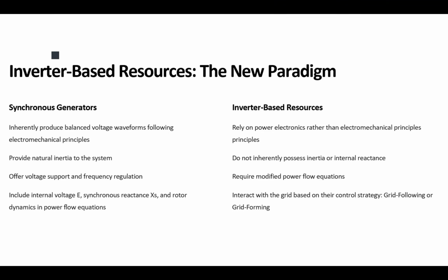We actually started talking about how we could analyze the effect of inverters from a system perspective, and we started with the power flow analysis, which is one of the steady state analyses for the power system, to find out what the distribution of the energy and power looks like and how the system would behave to address the variation in the load and generation and keep up with the generation-demand balance.